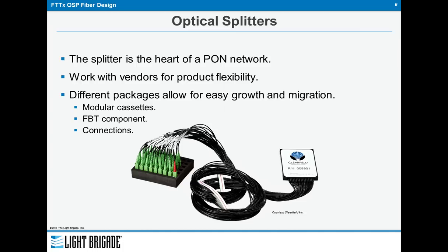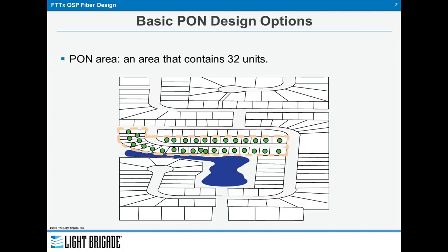So the payoff, the disadvantage, is that your distances are reduced in passive systems as compared to active, which, since you have a dedicated transmitter, can go without any componentry in between, start to finish. Typically, every time you divide the light, you lose about 3 dB of attenuation.